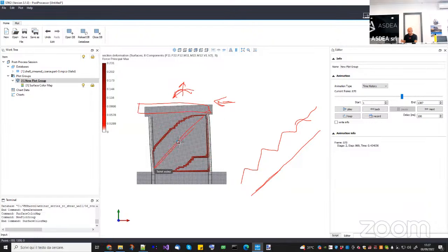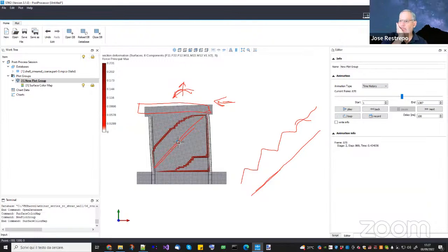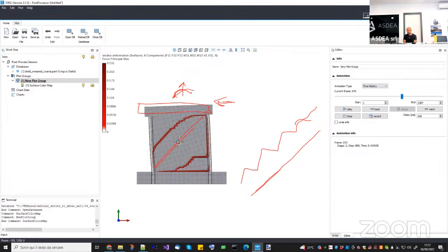But in this case, when you have a cantilever kind of load and a very squat wall, it is really a mess because the shear and flexure interaction is quite hard to capture. Then I didn't think about also the light reinforcement, which in this case makes the problem even more unstable. But yes, just to tell people that are approaching this kind of model, probably my mistake was to use the most challenging example. I should have used something a little bit easier.